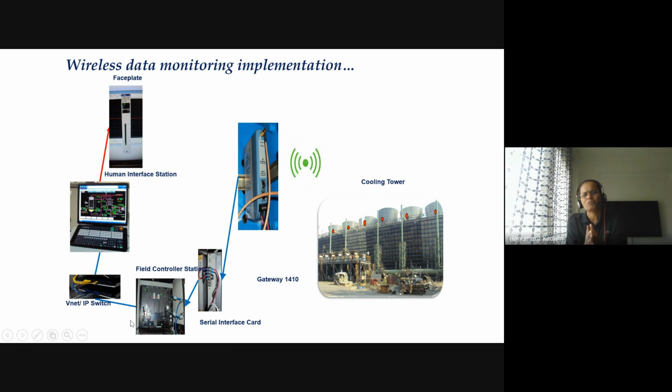RS232, RS485, these come under the serial interface category. You can see this card is there in the DCS, and then it is directly processed in the controller. This is the DCS controller, where you can have a modular structure with redundancy. Power supply two cards, controller two cards. In this plant there are two controllers, but two means one redundant, like this.